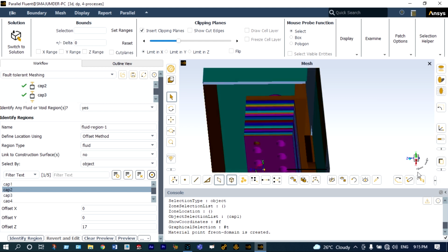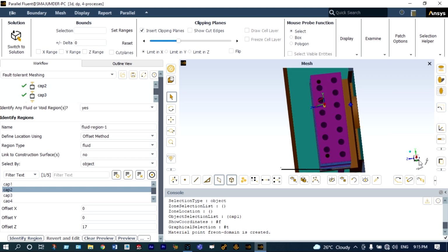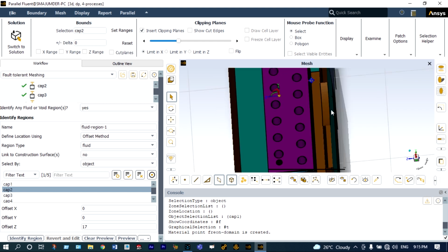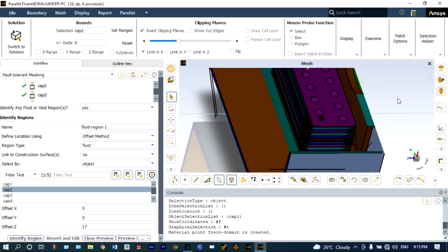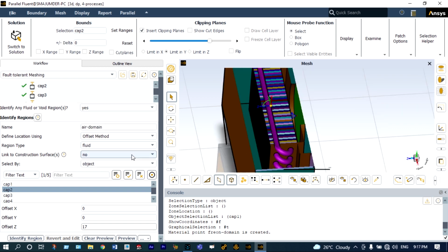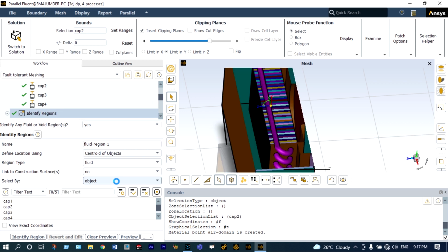You can see from inside this is the domain of air. This from backside will provide air at a specific rate, right? These air particles will pass through these fins, and it will cool Freon, right? So with this one, we can identify this is air domain. We can rename this one as air domain. Let us identify these 2 domains have been defined, Freon domain and also air domain.